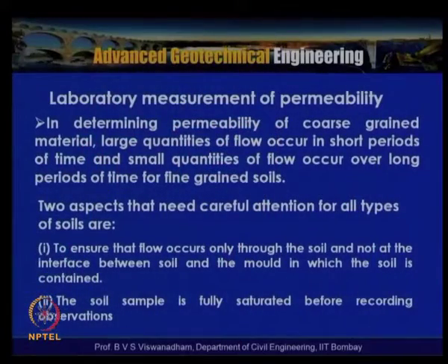Second, the soil sample must be fully saturated before recording observations. So whether it is coarse grained soil or fine grained soil, the soil sample needs to be completely saturated.